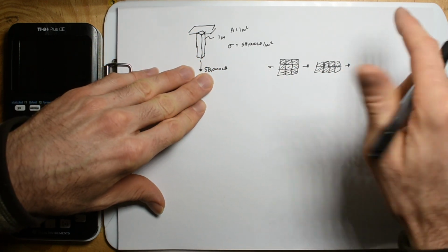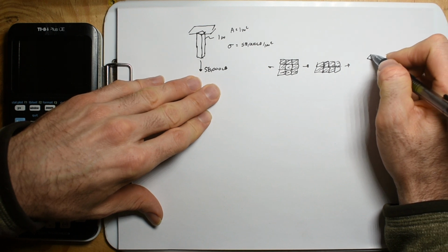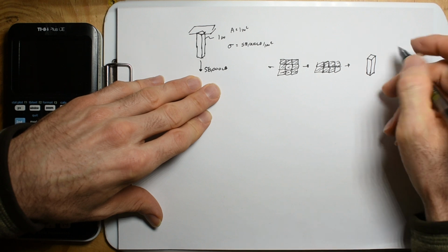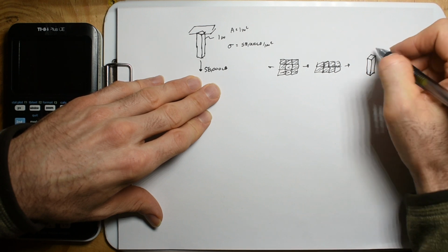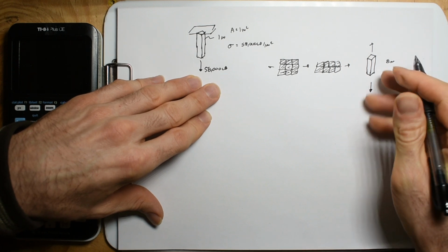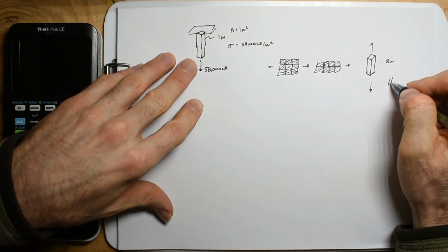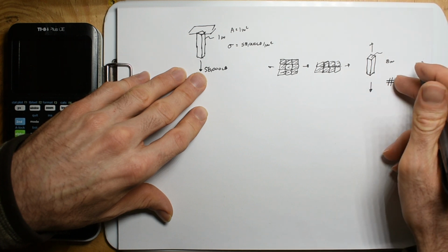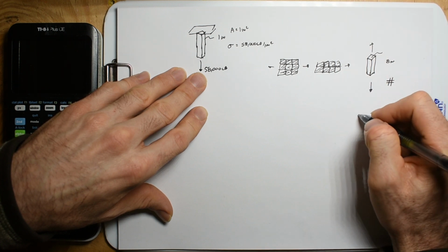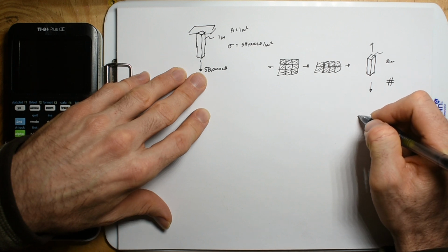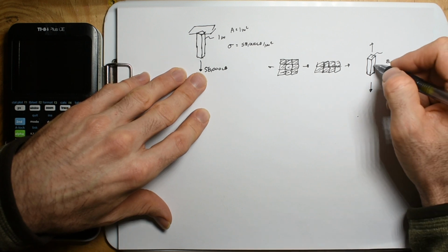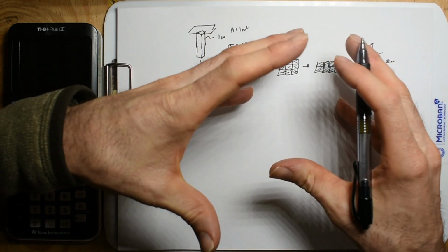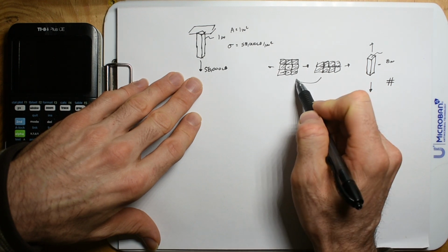And I will spend just a couple seconds on this advanced topic, because when you put something like a specimen, let's say this 8-inch specimen, and you're pulling on it this way and this way in a machine, you can put a max force, you know what I mean? So you're going to put a max load over an area, but then as it stretches, at a critical point it'll start to stretch, and that's the point where if you let go, it won't go back to the same shape. Once you get it like this, it ain't going back to there.